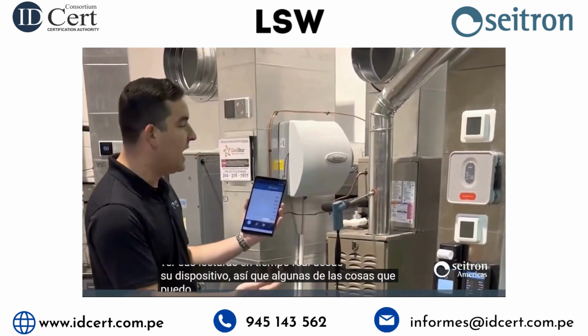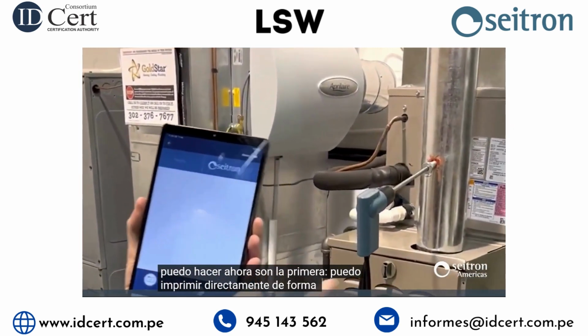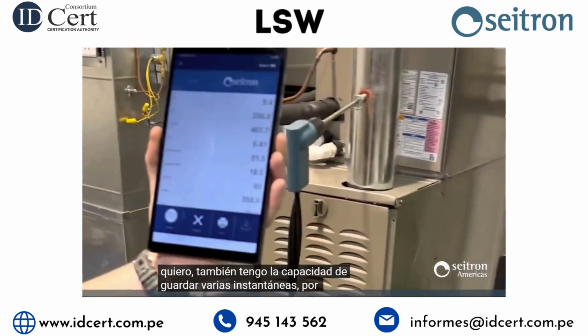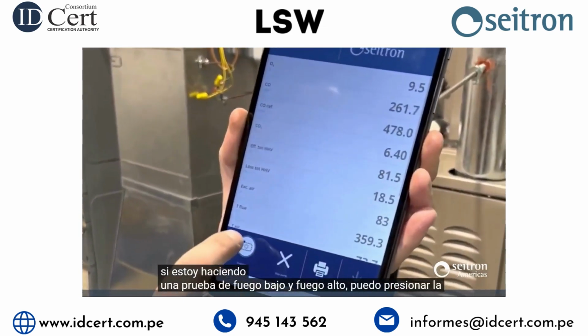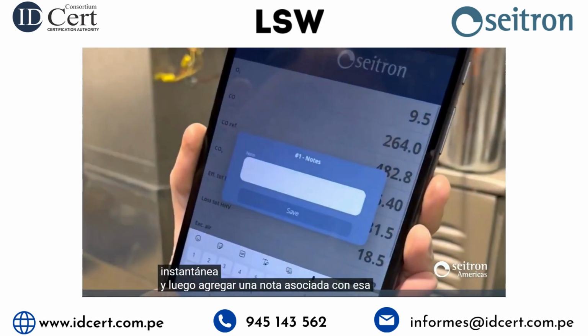So a few things that I can do now is, number one, I can remotely print directly to the combustion analyzer like so. Or if I want, I also have the ability to save multiple snapshots. So for example, if I'm doing a low fire and high fire test, I can hit snapshot and then add a note associated with that particular snapshot, right?